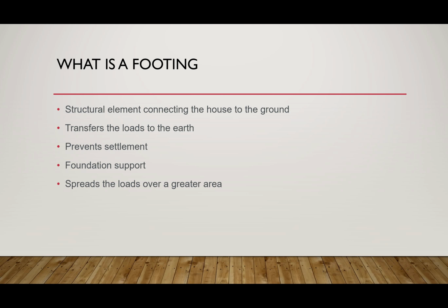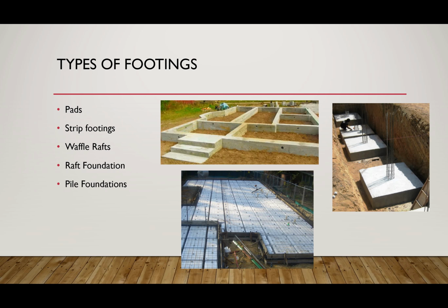So first thing, what is a footing? A footing is a structural element which connects the house to the ground. What it does is it transfers all the loads that act on the house, the weight of the building or any wind, brings all of that down to the ground. It prevents settlement of the earth underneath it, and it supports the foundations.